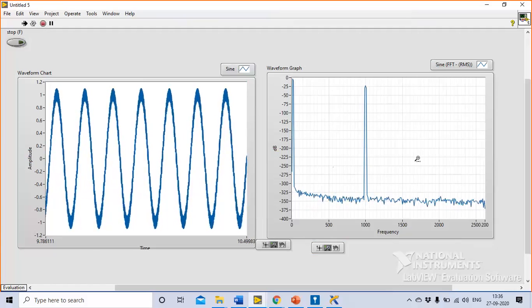Deepak sir? Yes, sir. I don't want to remove this noise floor because this is very, very minimal. Earlier it was at minus 40 dB, so it was a problem for me. But right now this signal is not a problem, but this signal is definitely a problem. So any cutoff frequency of a low pass filter below this peak would help me remove this signal. Okay, let's try that. That will be the last thing and then we'll break for lunch.